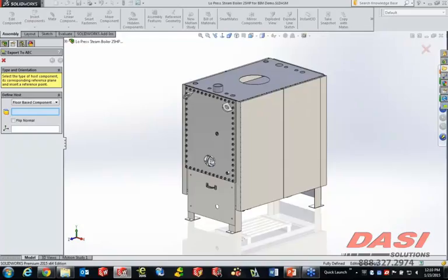Now, the first part here is orientation, and the reason this exists is because we are based on the Parasolid modeling kernel. And when you export to an AEC product, Autodesk Revit we'll use as the example, they are generally based on the SAT, the ACIS kernel. And ACIS defaults to the top plane, like you're looking at the Earth, which is a lot of what 2D architectural civil engineering products do. However, our Parasolid modeling kernel-based products like SOLIDWORKS and Solid Edge and Unigraphics, they all default to the front plane. So when we export this file as is, as a SAT file or ACIS file, it actually goes into the other products on its side.